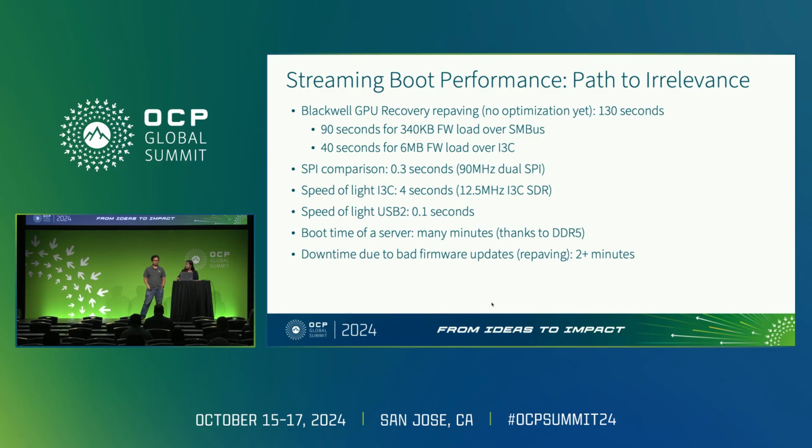All right. Hi, Varun. Thank you. I appreciate the effort over the years on this. So, how much SRAM is required now as a substitute to SPI NOR, since I believe that you will be chunking over the parts of the firmware, the management firmware down, and do we have a correlation that if we increase the SRAM size, how much bandwidth and how much timing it saves? And how about the case if at execution time the SRAM endures certain viral errors, ECC errors in the SRAM, then do we enter recovery again?